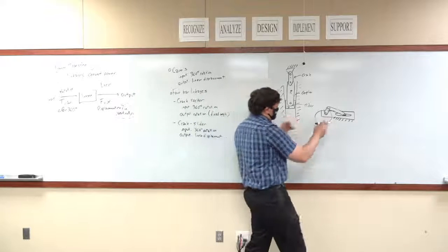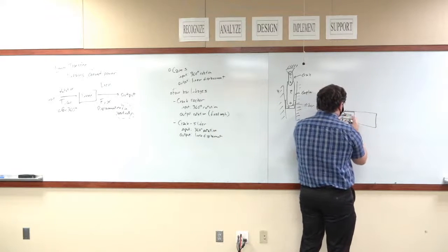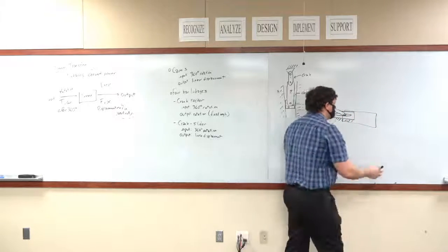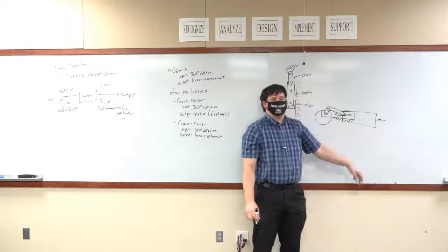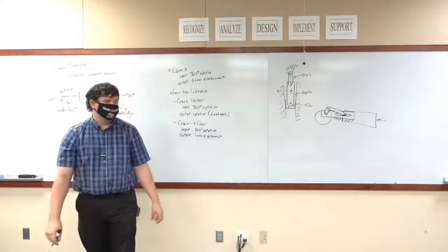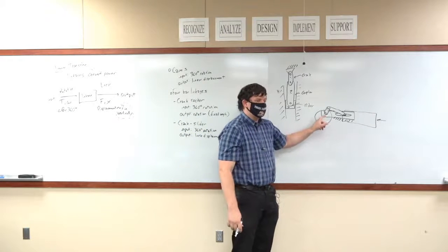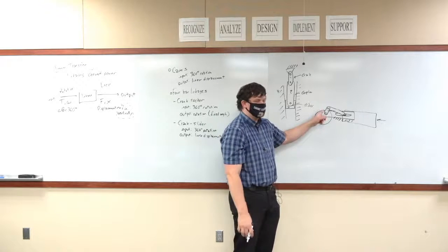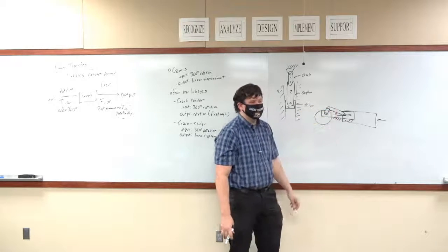Okay, so looking at this in the sideways configuration, let's say here's the rest of my leg. It is mounted directly to my sliders so that it can't rotate. What happens in this configuration when I apply a force to the bottom of this object? It's going to create a really large torque around this crank mechanism. Okay? In fact, that's the maximum torque that you can create, is when the crank is up and perpendicular to that coupler mechanism.